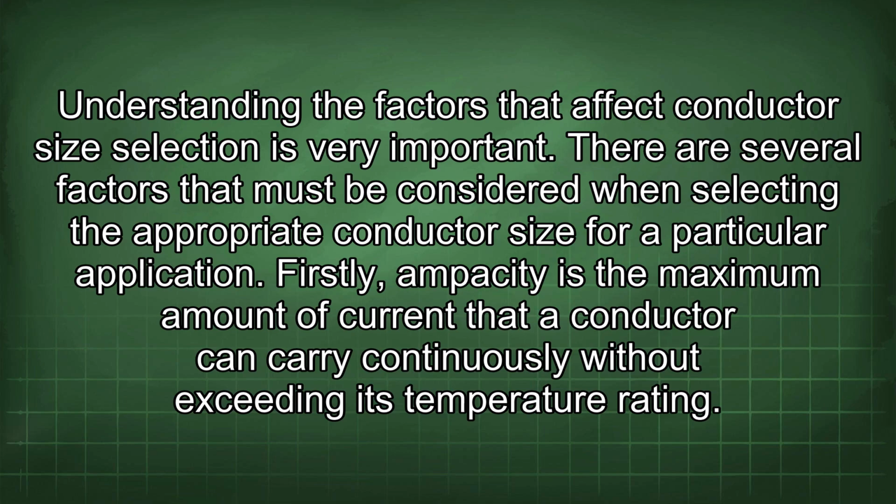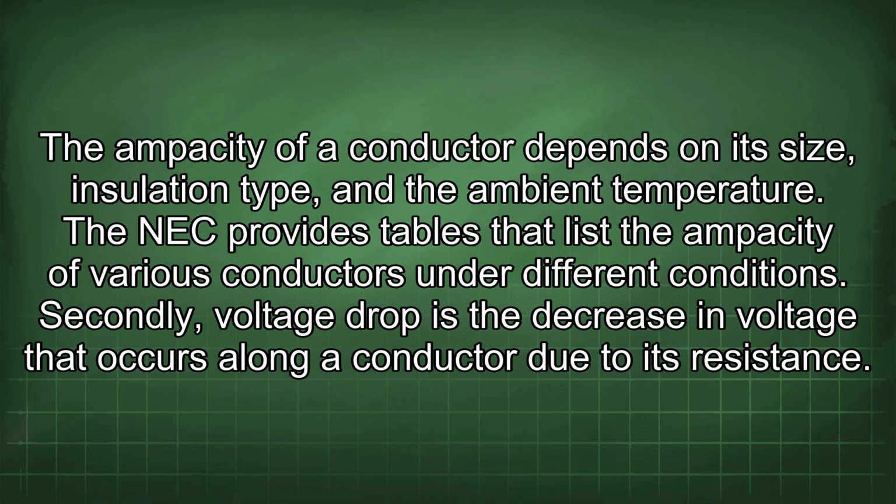Firstly, ampacity is the maximum amount of current that a conductor can carry continuously without exceeding its temperature rating. The ampacity of a conductor depends on its size, insulation type, and the ambient temperature. The NEC provides tables that list the ampacity of various conductors under different conditions.